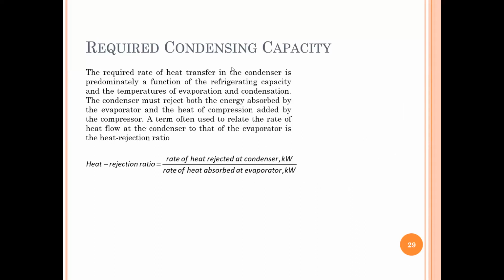So, the required condensing capacity. So, the required rate of heat transfer in the condenser is predominantly a function of refrigerating capacity and the temperature of evaporation and condensation. The condenser must reject heat, both the energy absorbed by the evaporator and the heat of compression added by the compressor. That is, condenser is equal to evaporator plus the compressor.